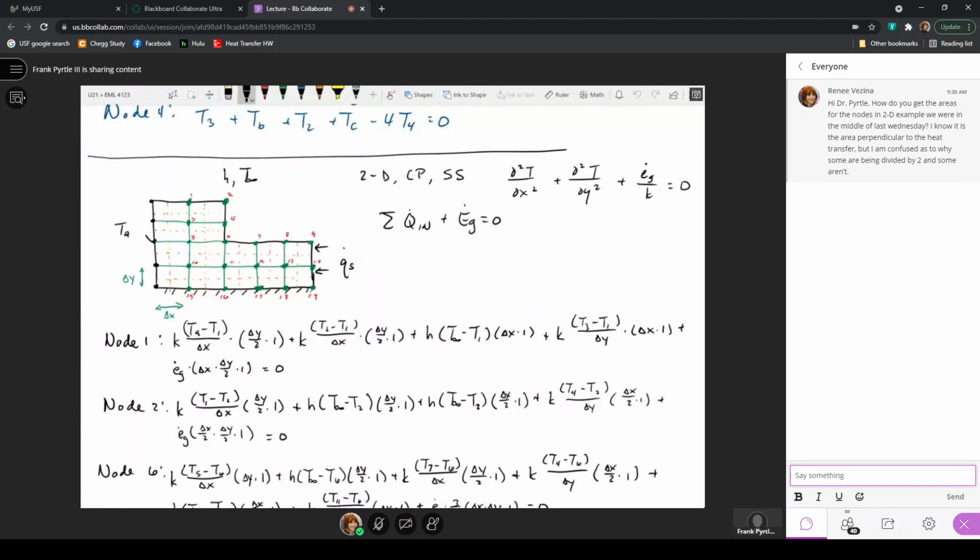Now here in green, I labeled all of the nodes for which the temperature is unknown. So on the left side of this bar, where the temperature was TA, I didn't need to label those. You could label them, and if this was node 0 here, node 0 would just have a temperature that says T0 is equal to TA. So rather than give these nodes numbers, we just use the boundary condition that the established temperature was TA. And we started writing equations for some of these nodes.